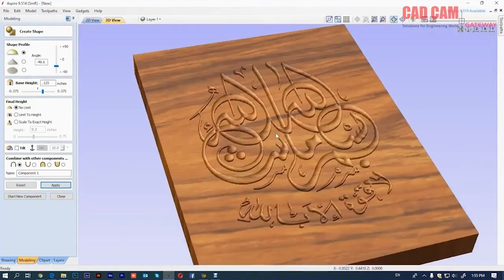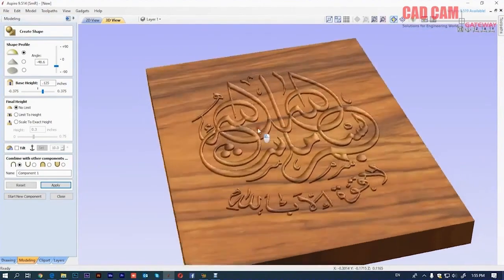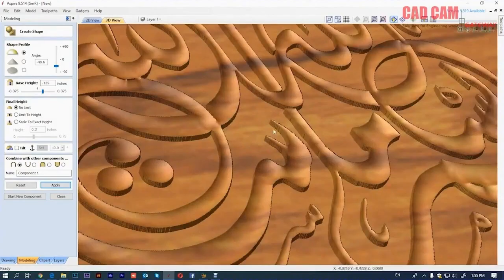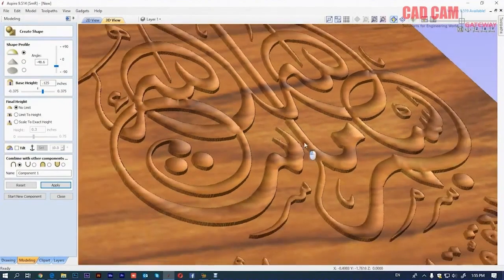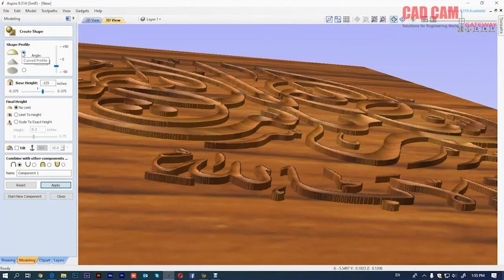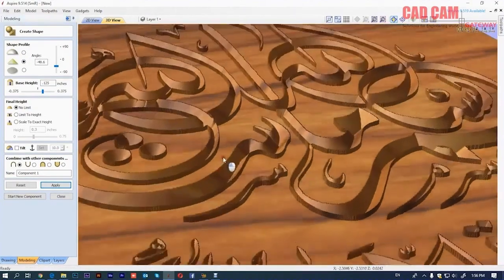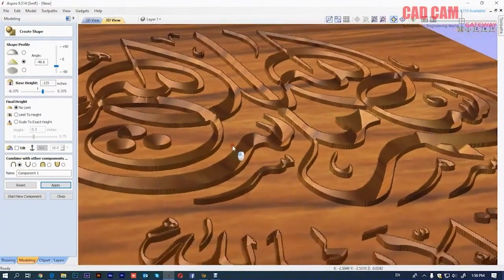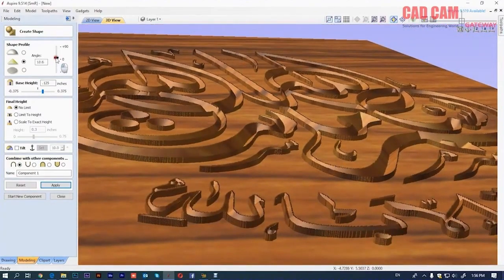Look, I am enlarging this window so you can see everything more clearly. See, the top part, as I told you before, is the profile, which defines the shape. So if you want to make it more angular at this point, you should switch to 2D mode. This will allow you to adjust the angles precisely, just as we discussed earlier. As soon as you make it angular here, since its angle is on the downside, if you move it to the side, you'll see it's loading and these values will shift to the side.